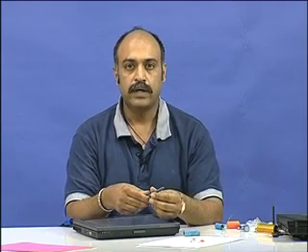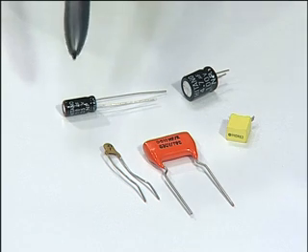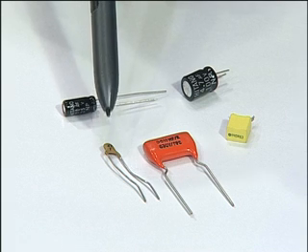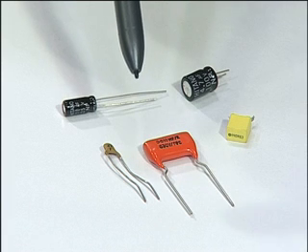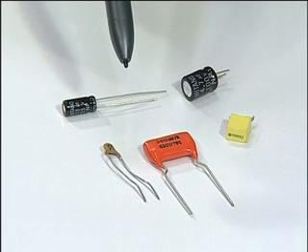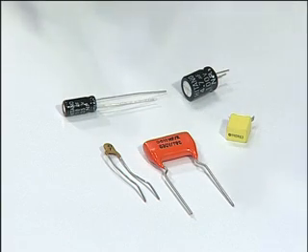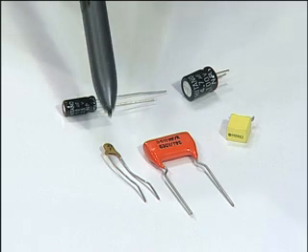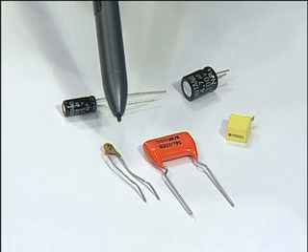Let us now look at some of the capacitors that you will find in the real world. If you look here spread out, there are a few capacitors. The smallest one here is a paper capacitor, and unlike, as I told you earlier, in the case of the resistors where you have the color codes for the values, for the capacitors the values are printed on the body of the capacitor itself. So, you need not remember any color coding for this. This is normally used for decoupling in electronic circuits.